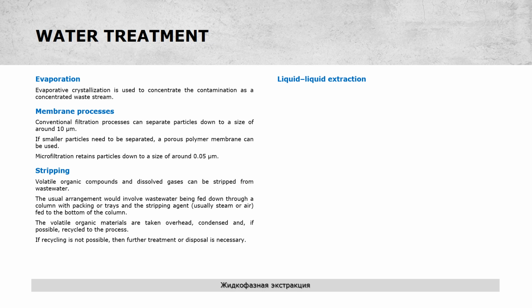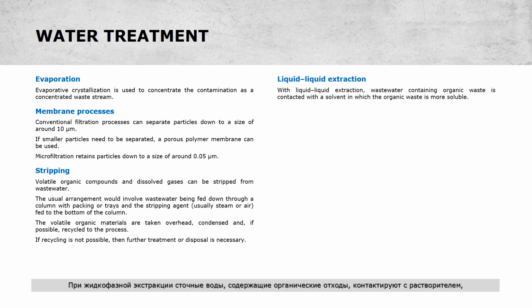Liquid-liquid extraction. With liquid-liquid extraction, wastewater containing organic waste is contacted with a solvent, in which the organic waste is more soluble. The waste is then separated from the solvent by evaporation or distillation and the solvent recycled.